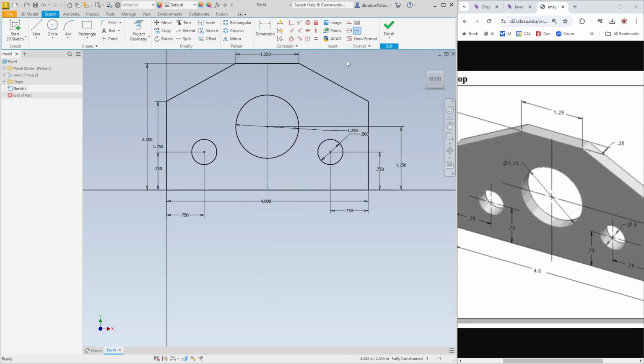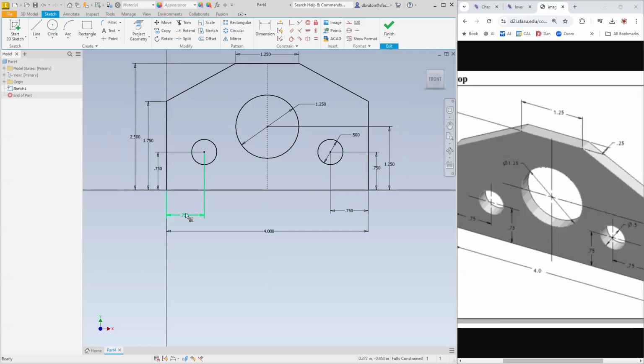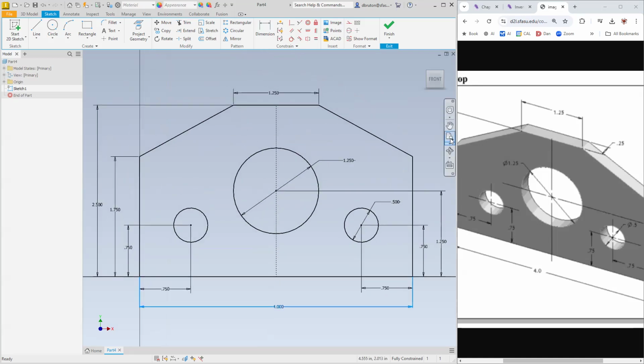Let's get out of any mode that we're in by hitting escape so we can reposition all of these to make the diagram look great. So from the inside out, small, medium, large. Try to bring them in tight so that when you print this out, the dimensions are not reducing the resolution of the big picture of the whole thing. All right, then we go over here and zoom all.